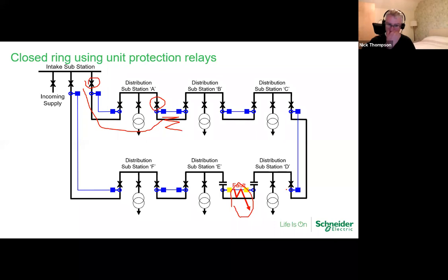Now, monitoring will come in various different forms. If you've got a SCADA system, you'll have the monitoring already there. You could quite simply have somebody walk around on a regular basis, i.e. once a day, and just check the status of the circuit breakers. That's another form of monitoring. Or you could put some simple other telemetry system in there where you constantly monitor what's going on with your network. Otherwise, you could take out half your plant or all your plant if you're not careful, and there are recorded cases of that actually happening in the past, and it will continue to happen as we go along.